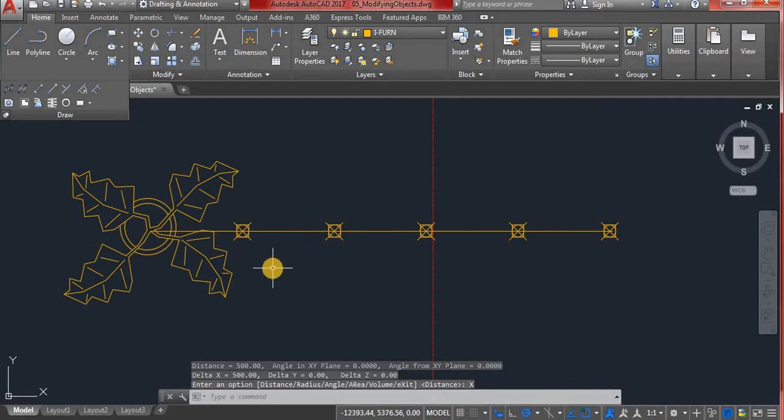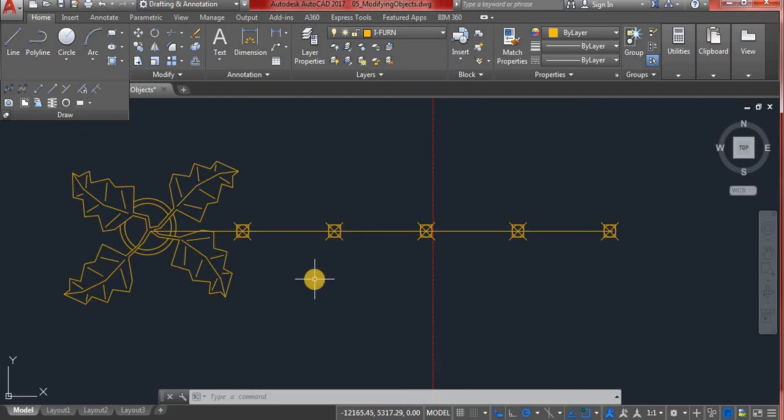So that's it. It's very simple, but you have to pay attention. The most important part is you change this point style, as I said, from utilities and point style, so it would stand out. I mean, a point will not show on that line, and you've seen in the previous videos. So pick a point style and go ahead and play with it. It's very easy, and actually it's fun. It shows you so many ways to deal with it.